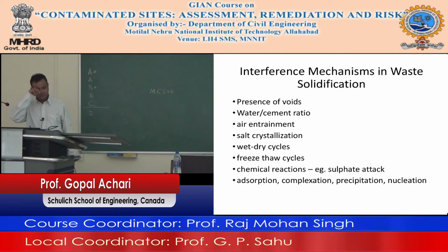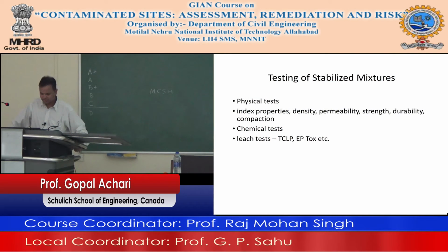Chemical reactions, sulfate attack. Because remember, your waste is a waste. You want to make sure that the liquid in the waste is not interfering with the setting of the cement, right? Adsorption, complexation, all that stuff. Testing of stabilized mixtures, physical tests. You need to find out physically, with soil-like material or whatever, the index properties, density, permeability, strength, durability, compaction. And you have to do the leach test, which is the leaching characteristic, toxicity characteristic leaching procedure, and EP tox test, and so on.